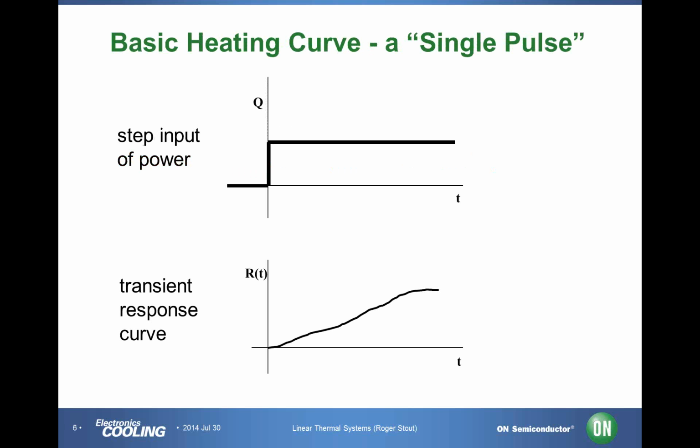And just to illustrate that, the basic response that we talk about in the thermal world is a transient step response, where we have a fixed power level that we just apply at time 0, and then we measure some kind of a transient response curve. So you will have seen curves like this all over the place. Using this very fundamental idea of a step response, basically we can synthesize the response to any power inputs.